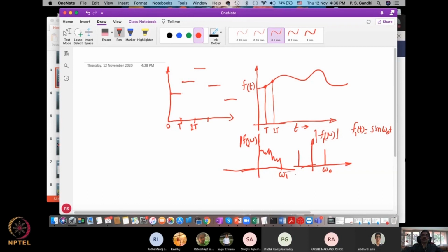We may need a little bit of refreshing of your Fourier transforms to really understand in great depth, or you can just have a feel for it. Say my signal is sinusoidal with a single frequency omega 0. In the frequency domain, I'm not going to see anything other than omega 0. That's the kind of physical sense you can have. If the signal has two frequencies, omega 0 and omega 01, then I'll see two peaks: instead of just one peak at omega 0, I'll have another peak at omega 01. Like that, I can see my signal having multiple frequencies depending upon the nature of the signal.